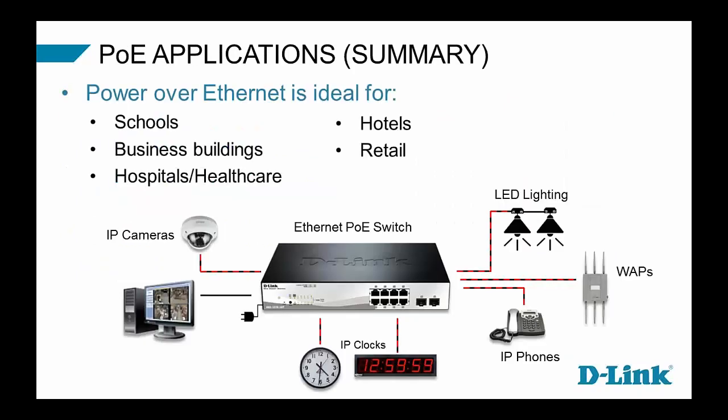So, summary on applications. PoE, it's really ideal for schools, business buildings, hospitals, healthcare, hotels, retail, anywhere that they're installing IP cameras or IP clocks, LED lighting, IP phones, wireless access points. Really a nice, simple to use technology that minimizes cable clutter, minimizes my costs when it comes to having to do permits and have licensed electricians come in. I can do most of this, if not all, by myself with my staff and my guys who run LAN cables all day.